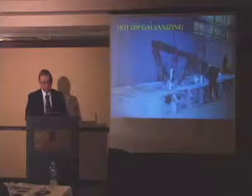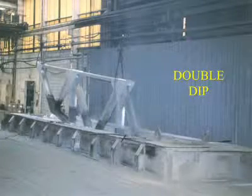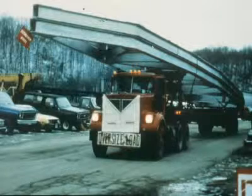In this case, they're pulling it out, cleaning it off and allowing it to drain. It's turned over, run through the flux line again, and acid washed on the other side. Then they're double dipping it. Once the coatings for galvanizing and painting have been installed, it's usually delivered to the job site.